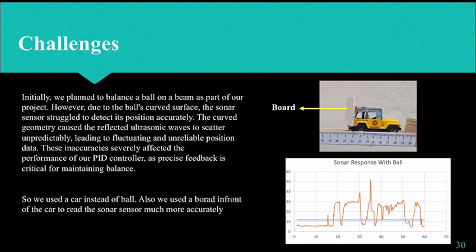Let's discuss the main challenges of our project. Initially, we planned our project as balancing a ball on the beam, but here we used the sonar sensor to measure distance, but the sensor HC-SR04 works on line of sight, and the ball shape is circular, I mean spherical. That's why the sonar sensor output data was really hard to capture.